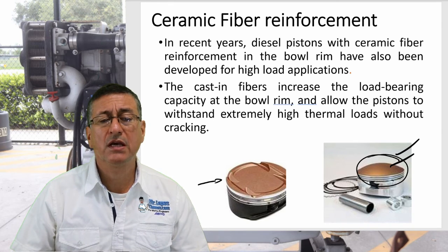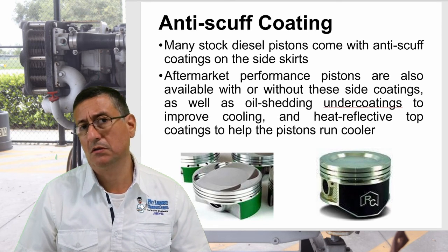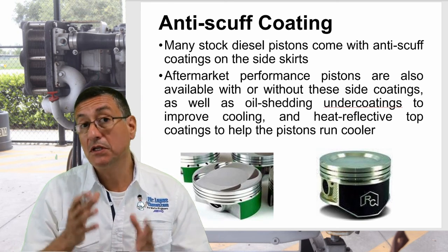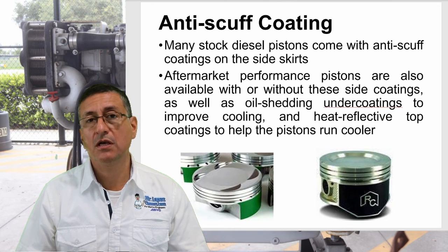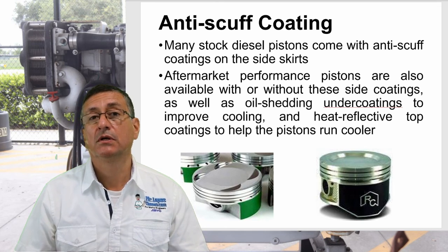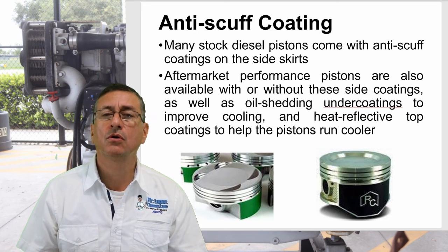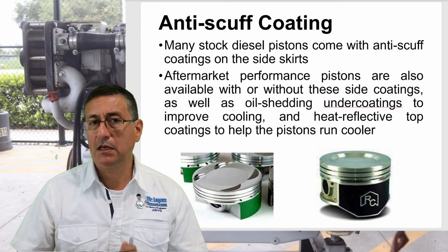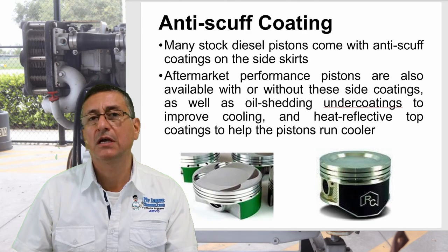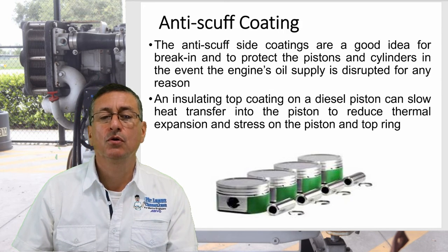Exactly the same with the anti-scuff. The anti-scuff is a lateral protection used in some medium or small diesel engines and gasoline engines. This is good because it reduces the friction in between the piston and the cylinder wall, and improves the cooling of the piston. This is once again good in medium and small diesel engines or in gasoline engines. Yeah, but in heavy diesel engines with supercharged diesel engines, I don't recommend that protection. It's good in medium and small diesel engines.